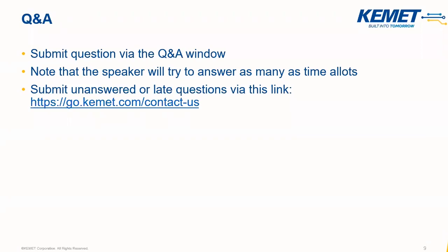Well, this is maybe a little bit easier to answer, because the only thing we are using in manufacturing an inductor is a piece of copper and a material around that. In the world of capacitors, it's much more complicated, and we always have the situation with lifetime. With an inductor, you don't have that many limiting situations. There might be a situation with humidity or temperature, but in the normal lifetime of any PCB, the lifetime of the inductor is not that bad an issue.